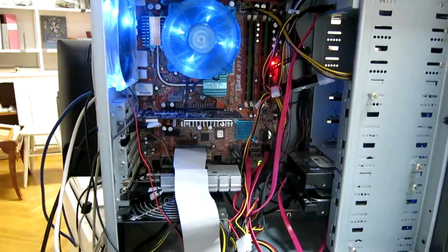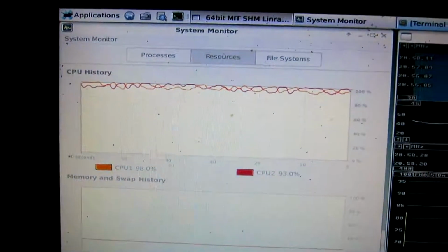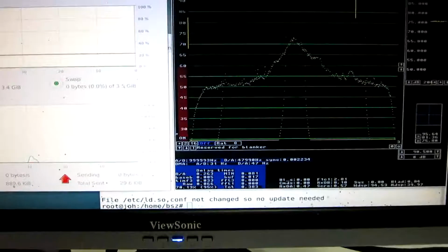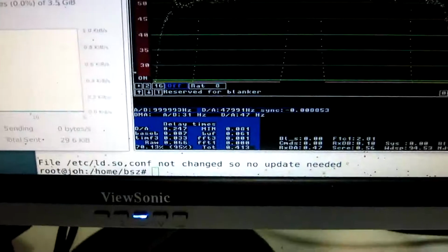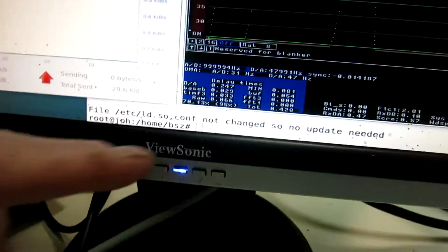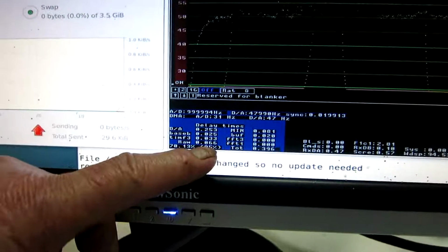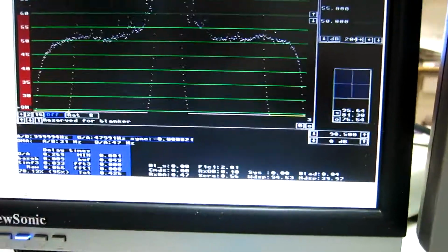This is a slower computer. It has 2 cores and they are both loaded close to 100%. I am running Linrad with the Blade RF at the sampling frequency of only 1 megahertz, as you can see here. The worst loaded core is at 95%. That is the FFT1 computations.